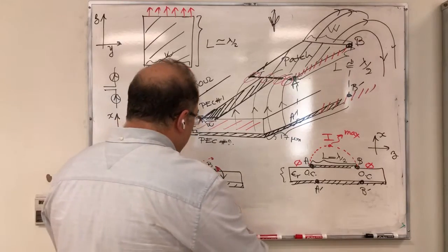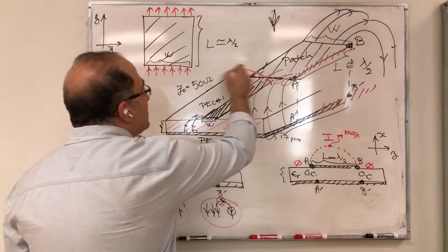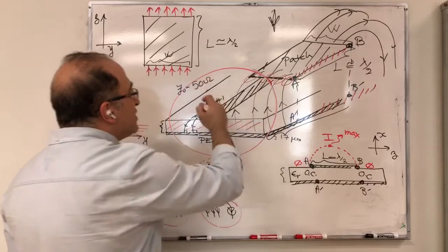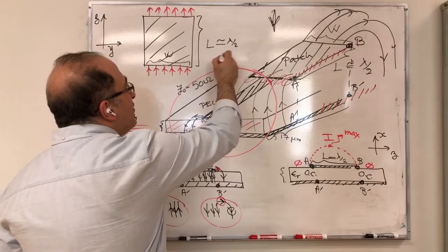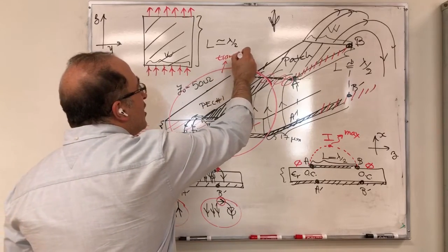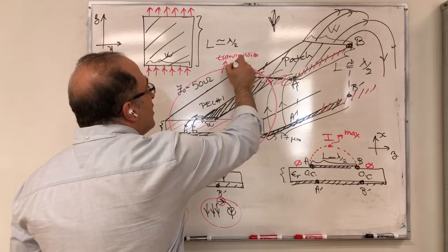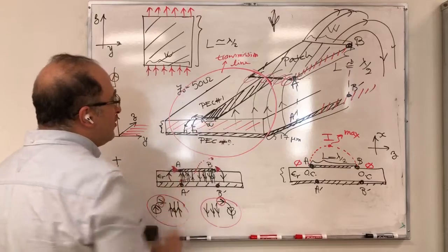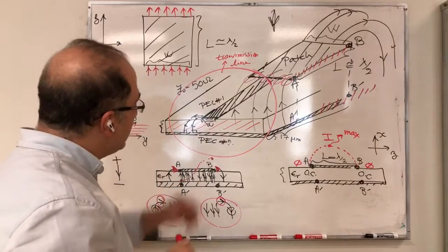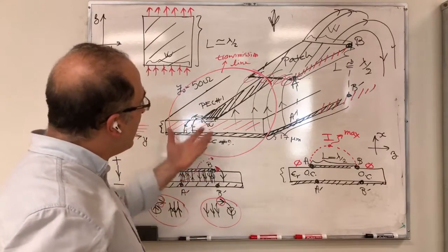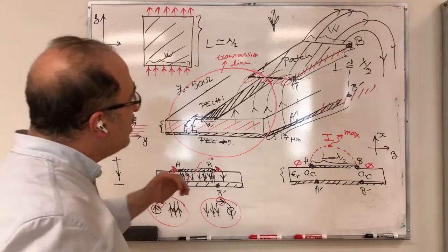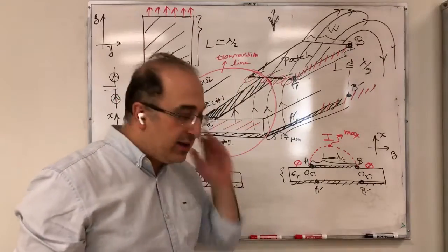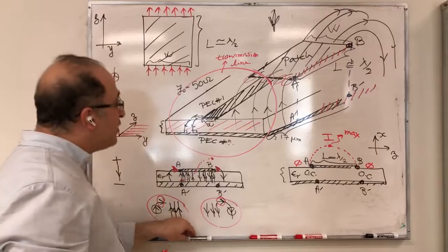This is our transmission line, and we assume that it's already been designed to have, let's say, 50 ohms. If you fix your dielectric substrate, then you have an appropriate width of this strip line to have a proper 50 ohms. So essentially, you end up designing the patch.